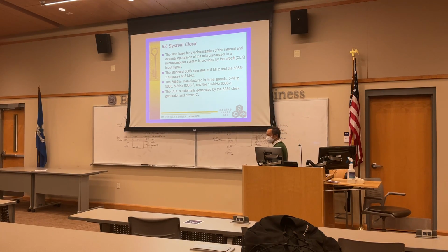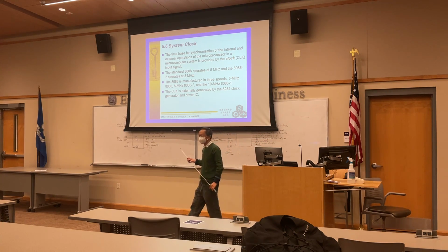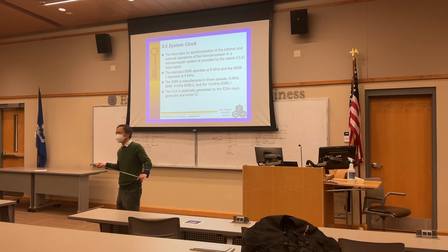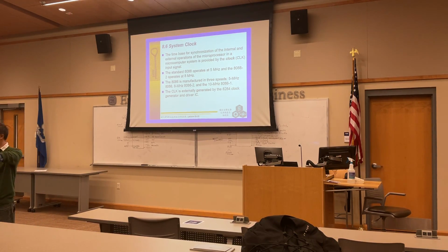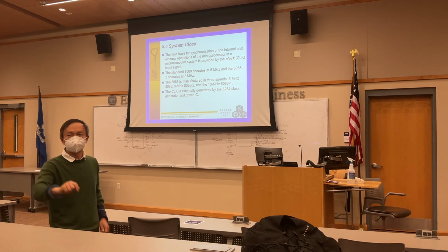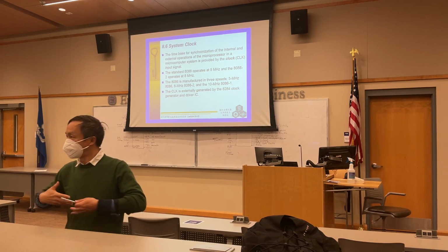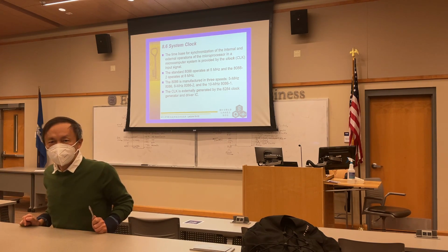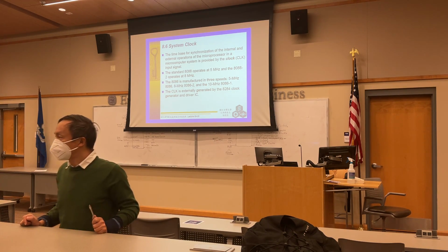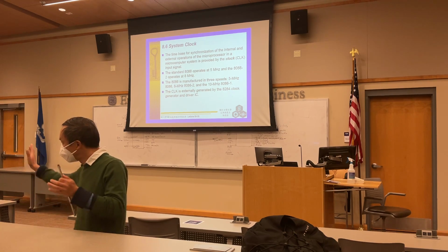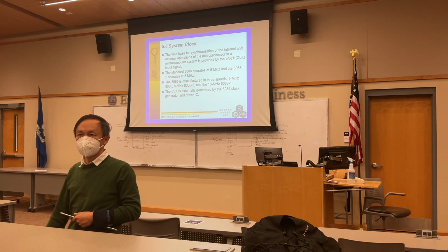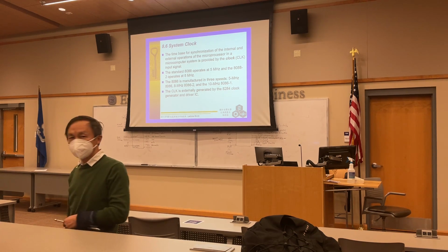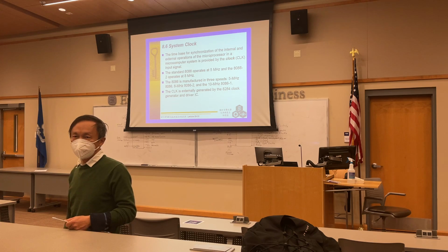Clock. Do we need a clock? We need a clock, right? Otherwise, we don't know what time to start, what time to finish. Clock synchronizes all the events and our behavior. Similarly, the microprocessor needs a clock because every event should be triggered to happen in a certain well-defined sequence. Don't mess up. If you mess up, then it's a nightmare.